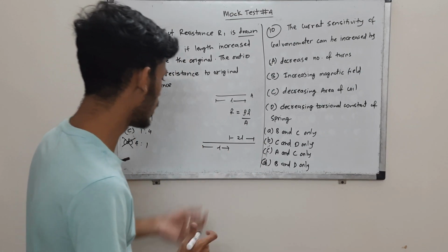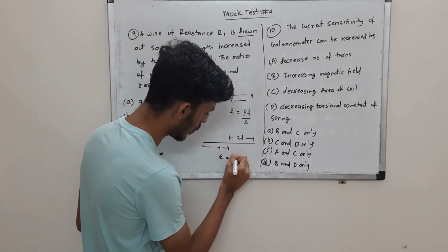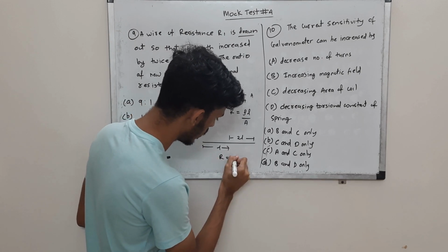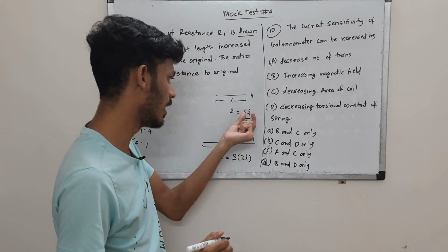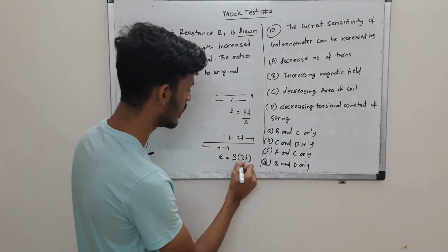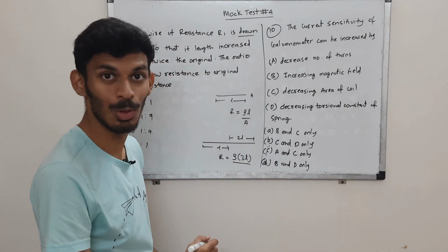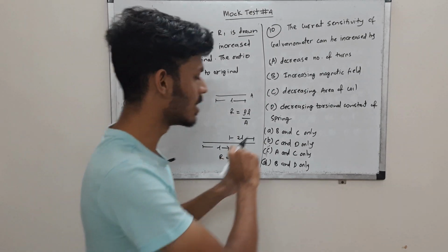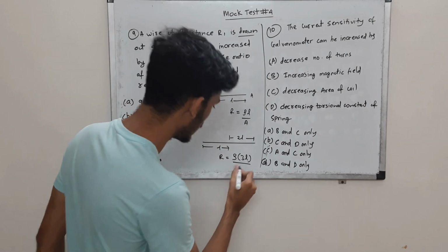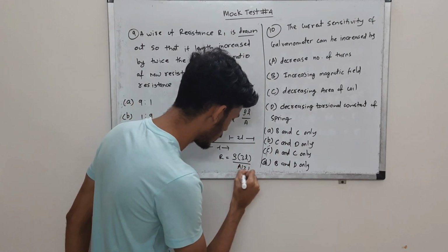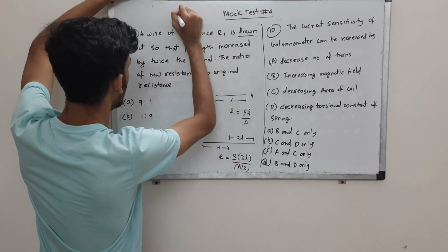Okay, so here the resistance will be rho, and the length is 3L, right? L plus 2L, rho 3L by area, right? What will be the area over here? Same A? No. Okay, the area will change because since you are stretching it, the area will decrease. Okay, and it shrinks to A by 3. So basically, A into L should remain constant.